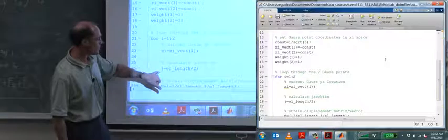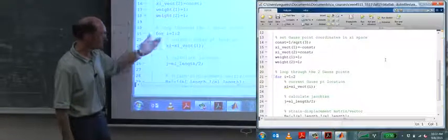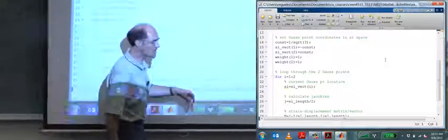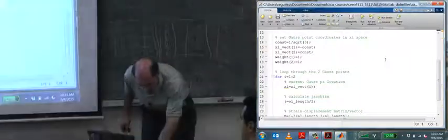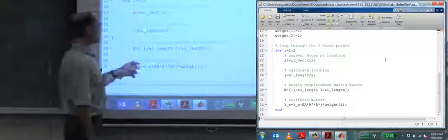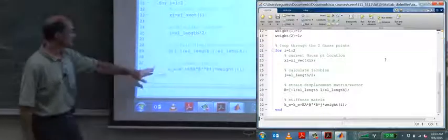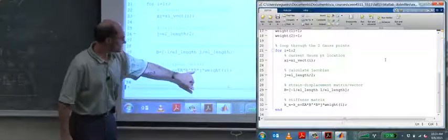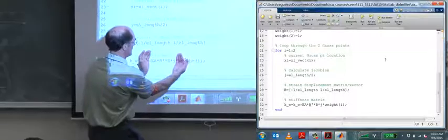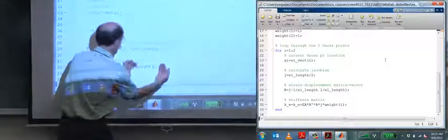Remember that our Jacobian of coordinate transformation, for this particular case, we formulated ourselves, so it's just directly programmed. It's the length of the element divided by 2, so you're going to see that JE come in. And then the strain displacement matrix is just negative 1 over the length, 1 over the length. We do the B transpose times B. We have EA. So this is our integrand right here, which includes the J. J happens to be constant, and there's our weight.